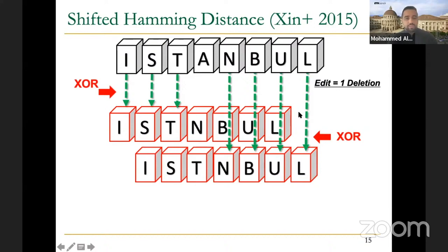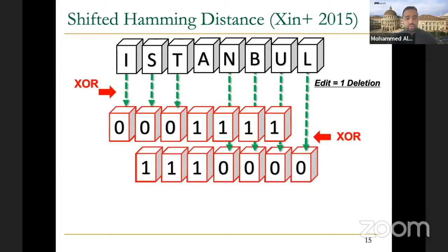How can we do this in an algorithm or in hardware? So the match operation, we can do it directly using XOR, right? And now this is the XOR result. If you convert the match into 0, because there is no difference. So in an XOR operation, if the number of differences is an odd number, then you always get 1, right? But since here they are always the same number of characters, T and T, that is even, not odd. That's why you got the 0 over there.